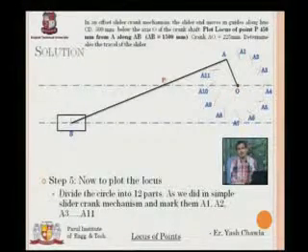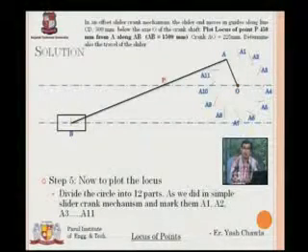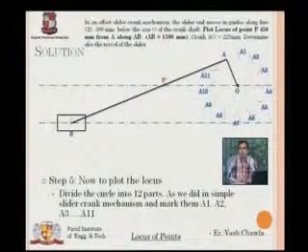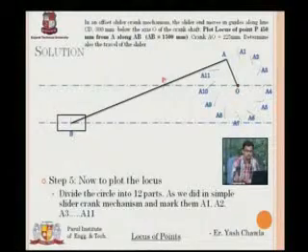Now again I have to mark different positions of the connecting rod according to that, different positions of the slider according to that, and different positions of P according to that. And once I'm done with that, I'll connect the points to get my locus. Here we go.